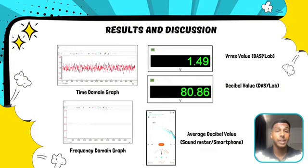The decibel value obtained using DASYLab is generally more accurate than the value measured with the Decibel X app due to the differences in hardware precision, software customization, and environmental control. DASYLab setups typically involve high-quality, calibrated microphones and professional-grade hardware interfaces. These tools are specifically designed for precise voltage readings and reliable sound measurements, ensuring that the data collected is highly accurate. In contrast, Decibel X relies on the built-in microphone of the smartphone, which varies significantly in quality and is not optimized for accurate dB measurements. Additionally, smartphone microphones are often uncalibrated, leading to potential errors.